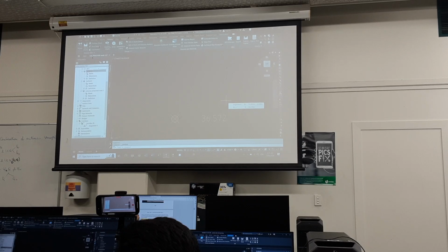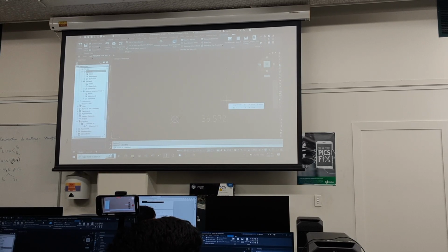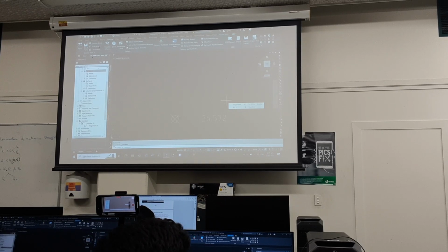Generally speaking, in layout space, the levels need to be about 2.5 millimetres, but you'll need to multiply that by the scale and work out what it is in model space. And generally, any text on your drawing should be 3.5, and any arrows. Also, your contour labels should be 2.5 as well.